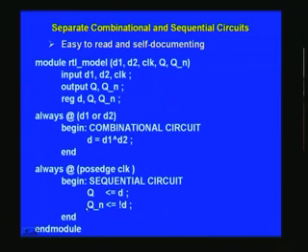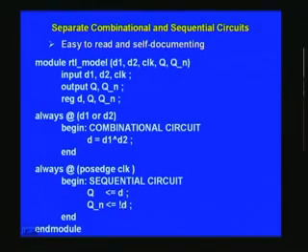although we are inverting, you will be surprised in the synthesis tool to find 2 flip flops there, not just 1 flip flop. Our intention was to make just 1 flip flop, and the other one is merely an inversion of this, but unfortunately the tool does not have that much intelligence. As a designer, you have to know the limitations of the tool and find ways and means to circumvent those limitations.